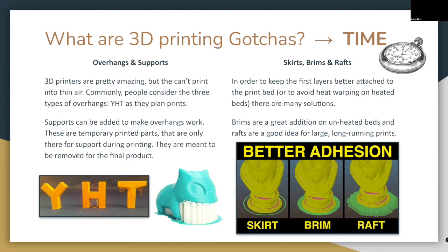I've had people with good success around me using PVA, but I'm not a giant fan. And then next up on the right, one of the big things that's another gotcha is if your piece doesn't stick to the bed. So I said, don't leave until you've got a couple layers down. And that's really because the first few layers are really important for your print.